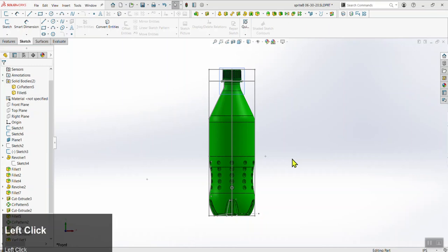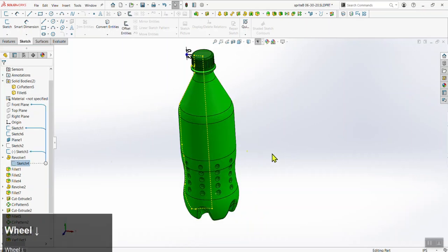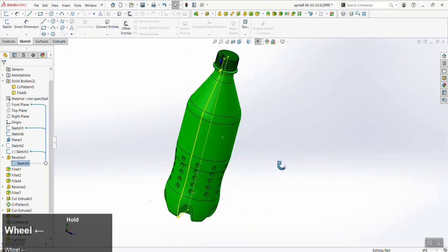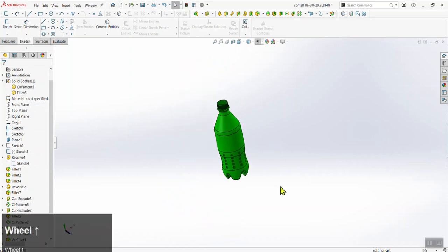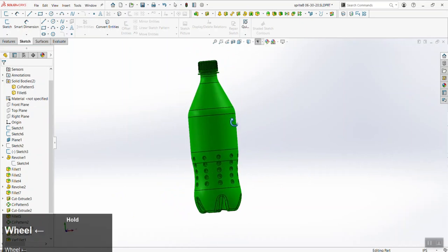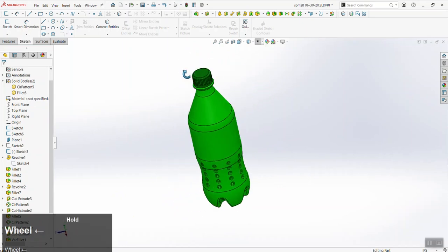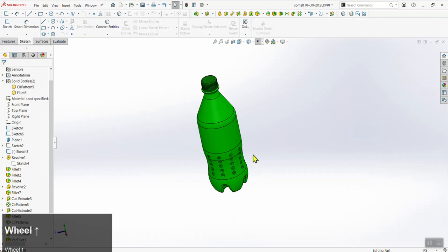Hello, this DES 450 demo will cover the introduction to SolidWorks and then get into sketches specifically, which is a feature that all the 3D elements of SolidWorks are based off of. Firstly, navigation within SolidWorks. I'm using the center mouse wheel to zoom in and out, and then clicking down to tumble the model. We can see our model in our center window here.